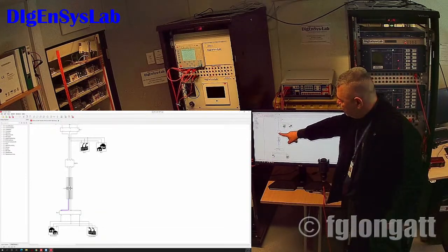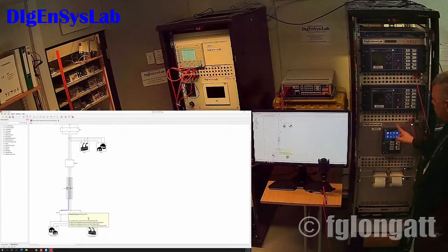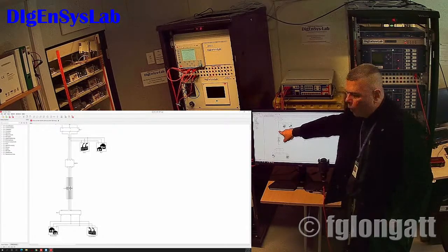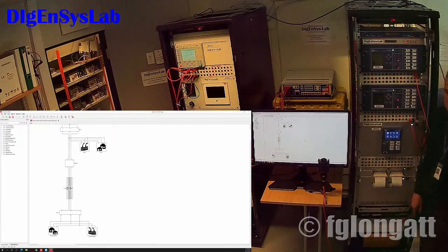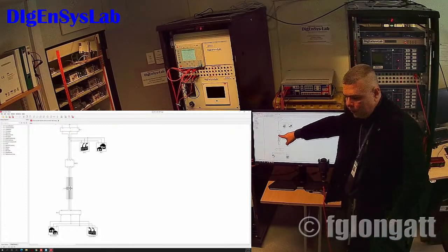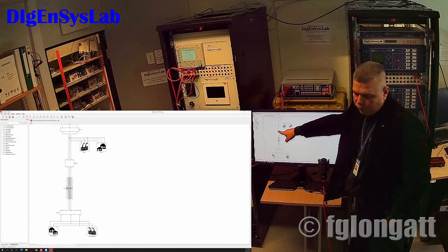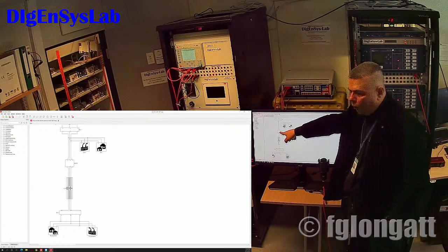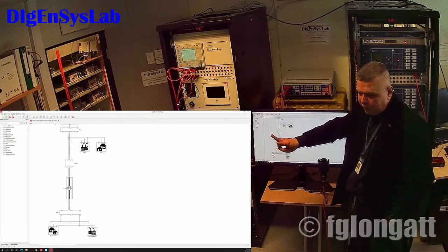This guy is sensing signals going into the relay, and if the relay sees that the current is above the pickup, it will send a signal back. And it will tell the circuit breaker to open and disconnect everything below, okay? For that reason, if we have a fault here or here, this relay should see the short circuit current and automatically go above the setting, and this guy must open, okay? Two things that we need to realize, okay?